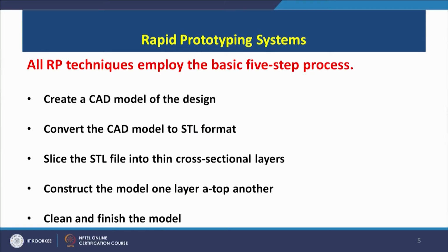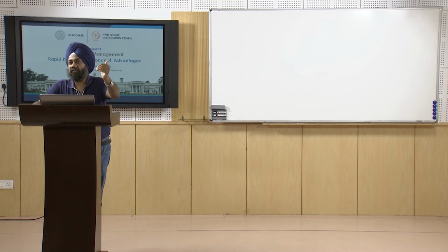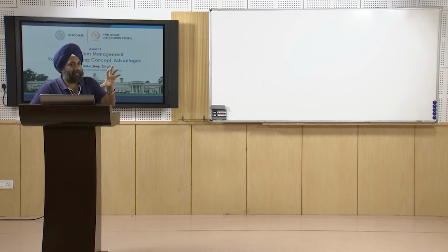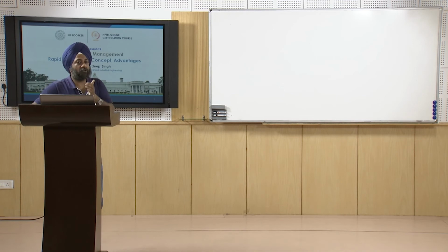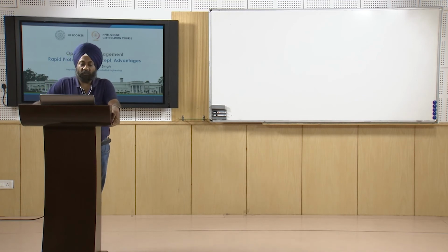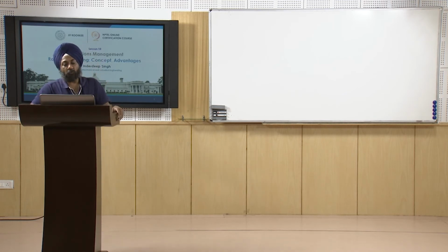These machines understand a specific language only, therefore whatever CAD software we have used to design the product, we have to convert it into a language which the machine can understand. So we have to convert that model to the STL format. Now we have to slice that STL file into thin cross sectional layers.